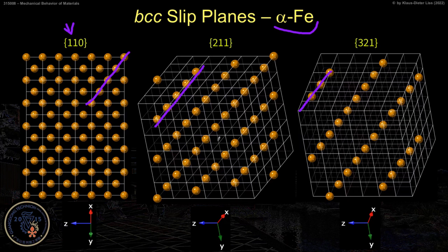You see the lateral spacing of these lines is different for the 3 planes. However, along the <-1,1,1> direction, we always have the same spacing. So you can imagine if you put a Burgers vector in here, or in here, or in there, in first order, it's a similar amount of energy we need, and how much energy we need depends minutely on the bonds between the atoms.